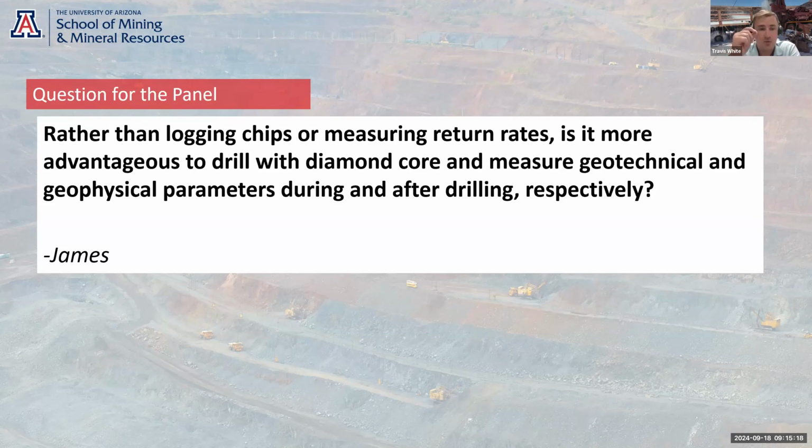It can then also give you an indication of where there's structure, at what depth, at what orientation, so that if you move away from that hole, you know in which direction to move and drill your percussion hole or your large diameter RC hole. So I wouldn't say more advantageous. I would say it should be done with your larger diameter drilling, and ideally done beforehand, right? So this should be the precursor before you go drill your large diameter hole.